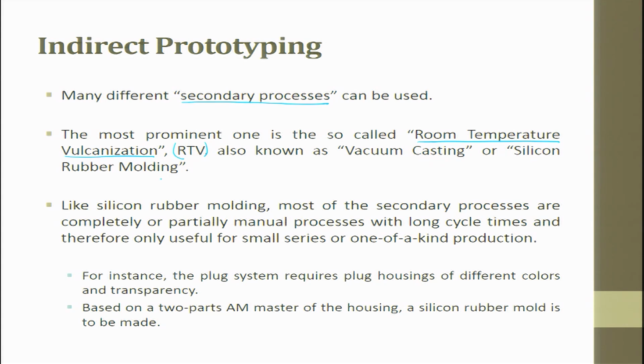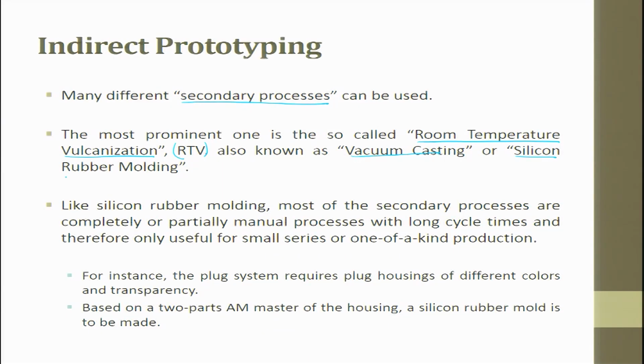In the introductory lecture, I was talking to you about the ear which we made for the left side. What we did was the right side scanning of the ear, and then we did some tweaking with the help of the doctors. Then we made a mold by rapid prototyping, and then we used this technique called vacuum casting or silicon rubber molding to get the output we wanted. So, that is nothing but indirect type prototyping. In fact, it is indirect type manufacturing itself that we did.